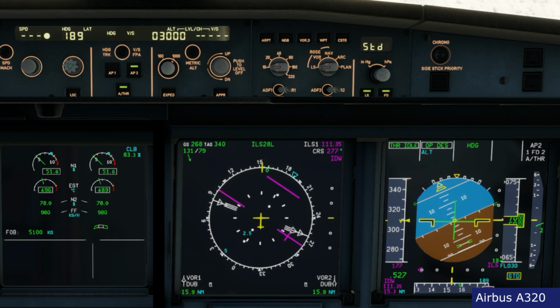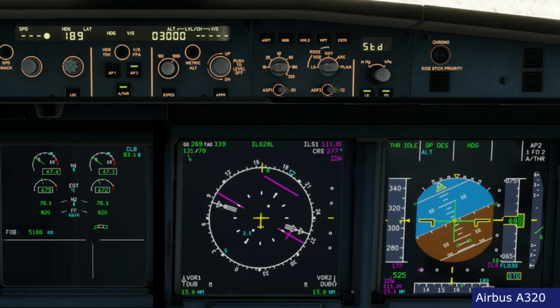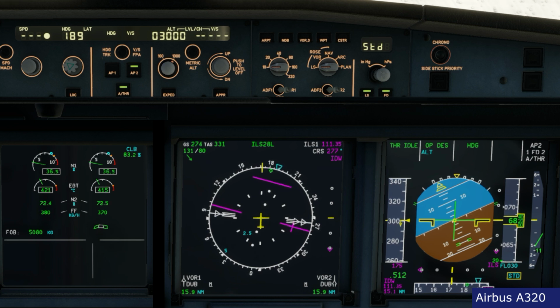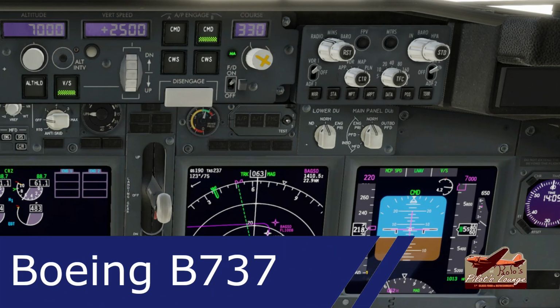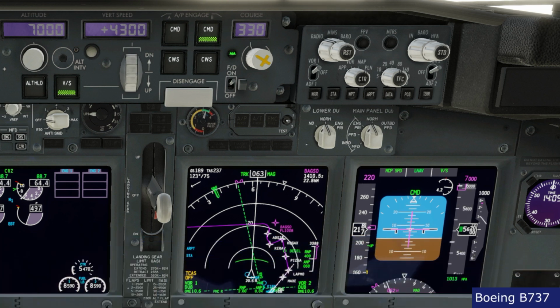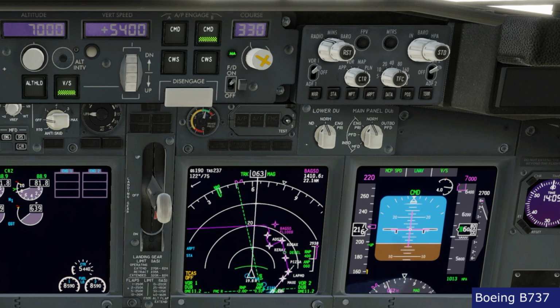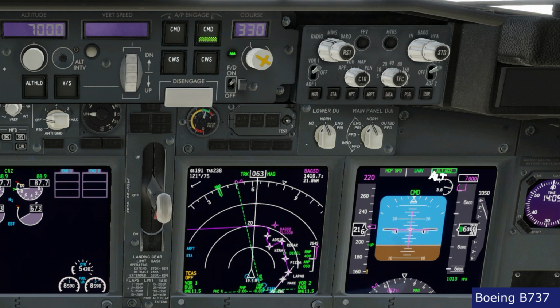So changing the altitude would not cause the aircraft to descend. I have to take an action, either an open descent, a vertical speed, or a managed descent through the FMS. If I don't take an action and just select the altitude, the aircraft would not actually climb or descend to the new altitude. The altitude hold has a transition function, which is the altitude star or the altitude acquire on the 737. The altitude acquire, or the altitude anyway, is always armed on the 737, so we should see continuously white altitude arm here. You should imagine an alt there, white, which is continuously displayed.